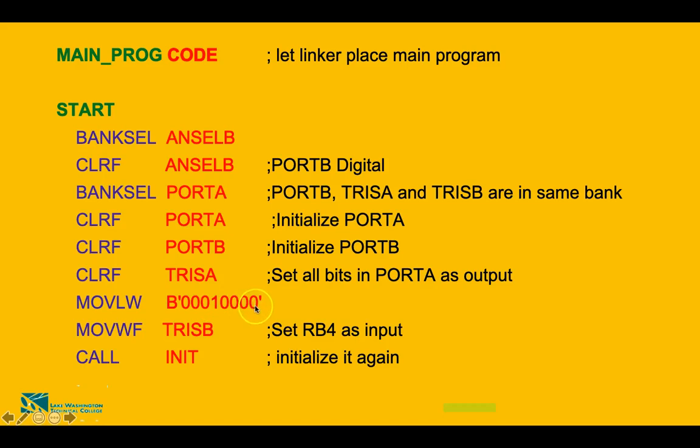You remember this is RB0, RB1, RB2, RB3, RB4, RB5, 6, and 7. So RB4, you're setting RB4, and every time in your TRIS, if you provide 1, or if you set any 8-bit data in a TRIS, that means you're providing the input.